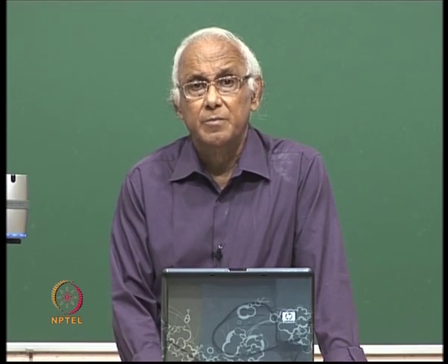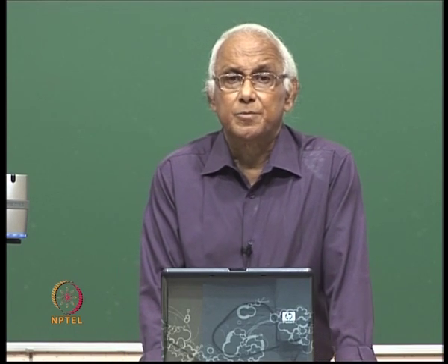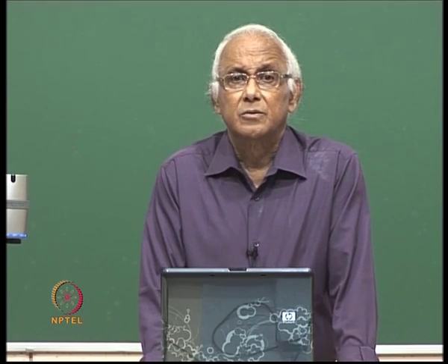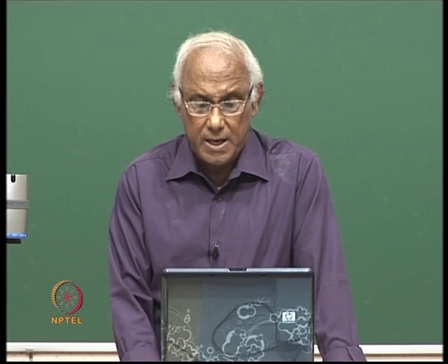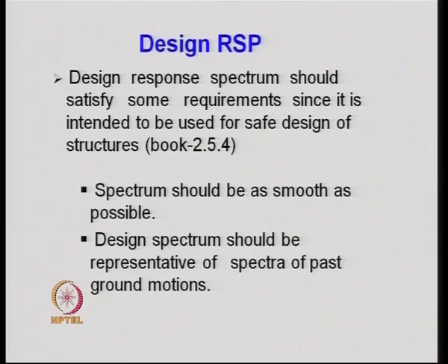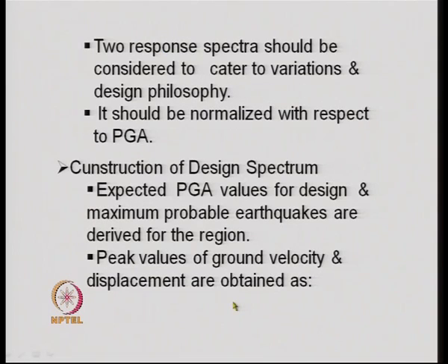In order to eliminate that, the design response spectrum is considered to be as smooth as possible. Then, the design spectrum should be representative of spectra of past ground motions that we explained before.